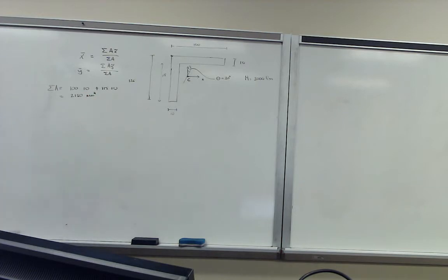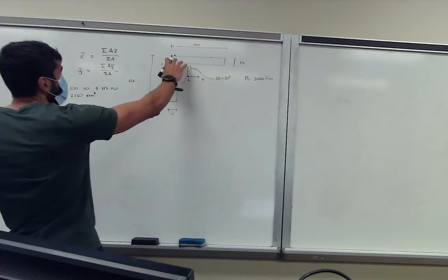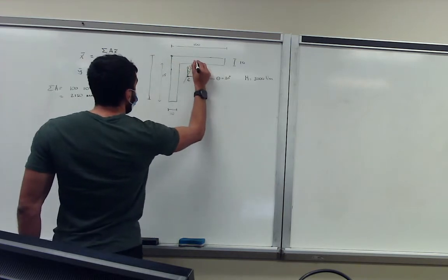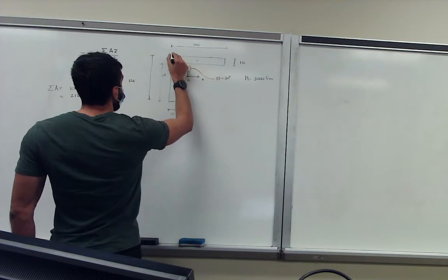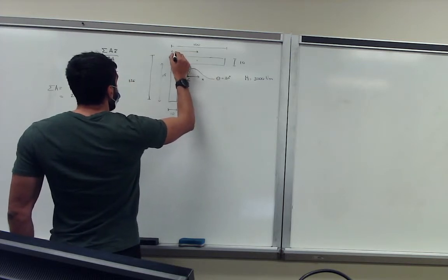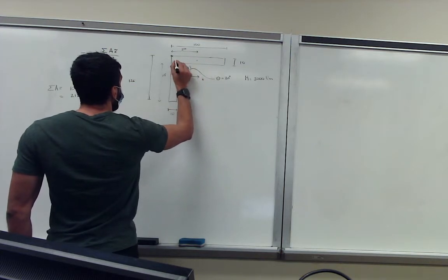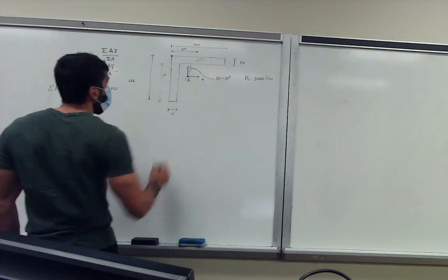And then let's do the x-axis first. Let's take this as reference. What's the centroid of our horizontal beam? Basically, the centroid will lie in the middle, so we can draw it here. By definition this is in the middle, so this will be 50, and the height of this section will be 5.